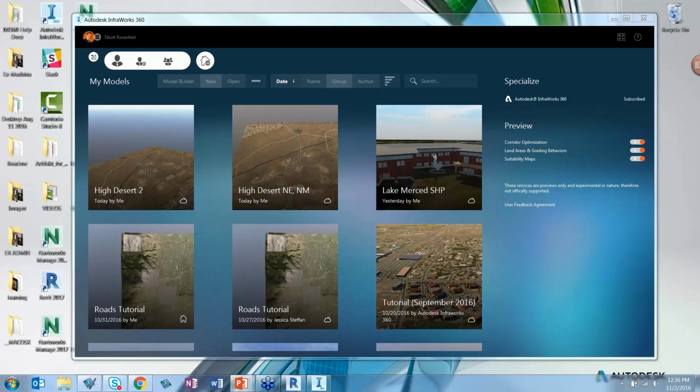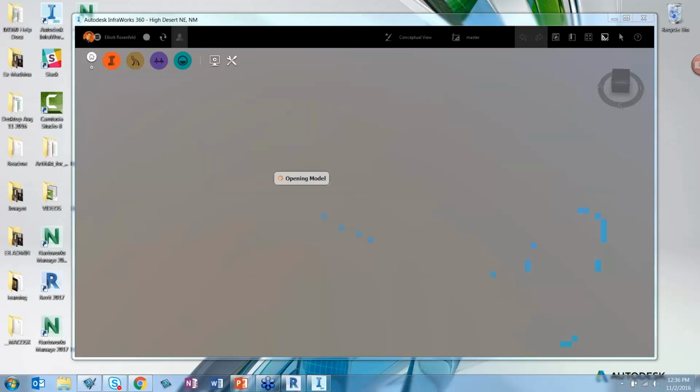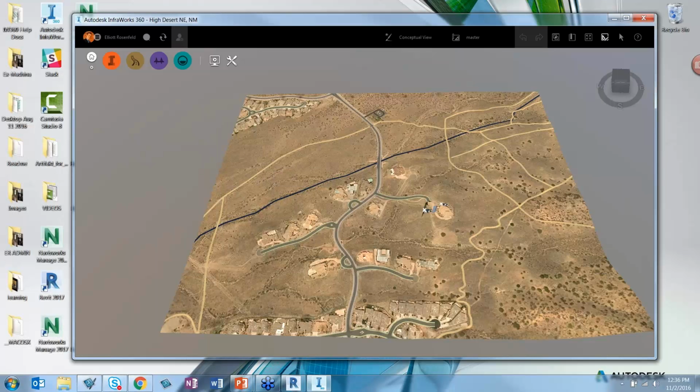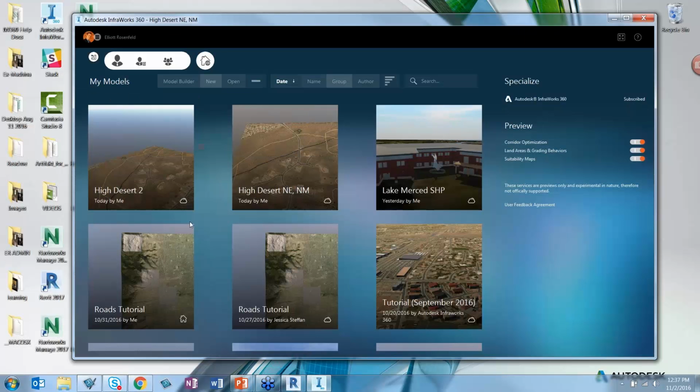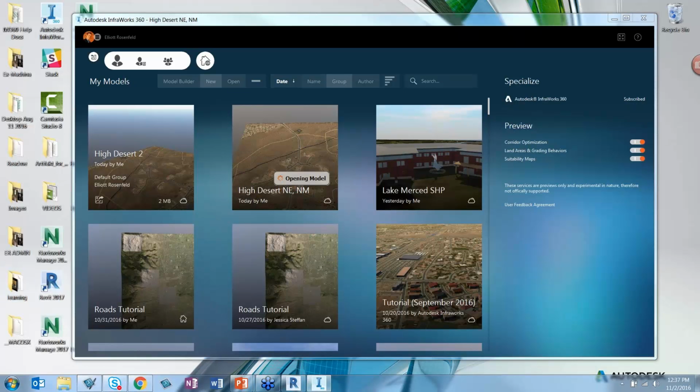Another question here is, if I export to FBX or Collada, will it keep the locations and rotations as well? That's a good question. DAE I wouldn't recommend for this workflow. FBX or IFC are acceptable options. However, the workflow that Willie just showed us with the RVT file format is the most intelligent option, and in most cases it's the one you should be using, unless for some reason you can't. Say that you have an FBX file and you need to use that. I can show you how we can do that.